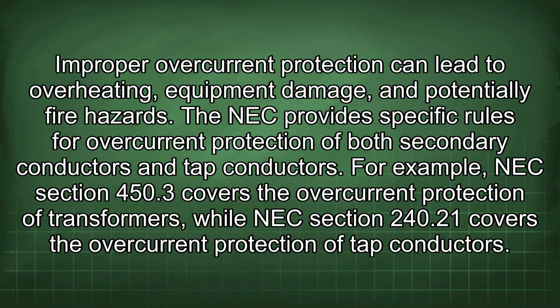The NEC provides specific rules for overcurrent protection of both secondary conductors and tap conductors. For example, NEC Section 450.3 covers the overcurrent protection of transformers, while NEC Section 240.21 covers the overcurrent protection of tap conductors.